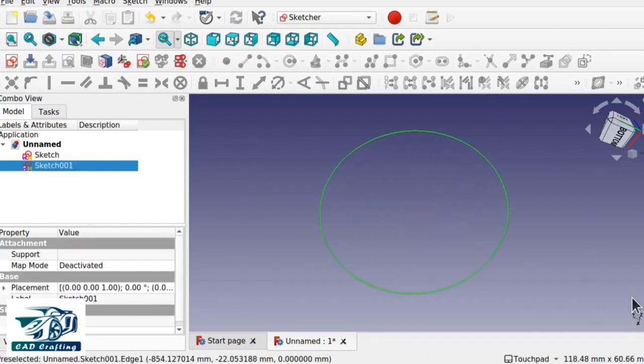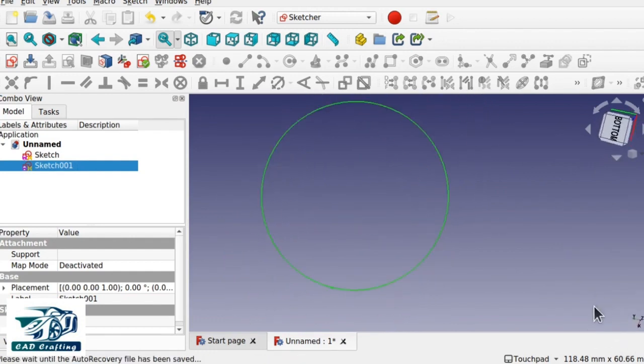Now if we look down on the right hand side, we have an axis controller down here, axis handler. This tells us whereabouts we are in 3D space, and this reflects what's on our cube at the top. So we can come around, let's click on bottom, you can see we've got the axis sitting there, and we've got green, red and blue for the different axes, so the Y, X and Z axis. So at the moment the Z axis is running this way, and the X axis is running down, and the Y axis is running this way, and it's reflected over here as well. We can see that we've got the red, the blue and the green.